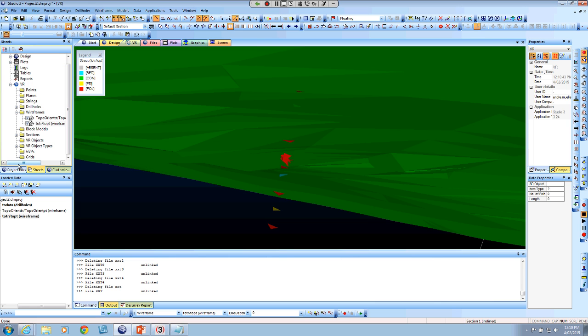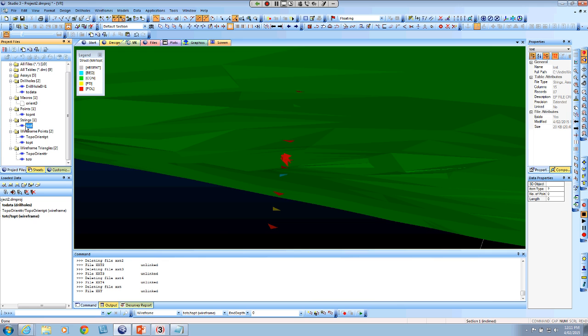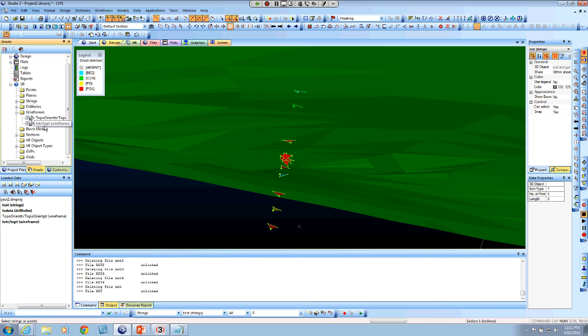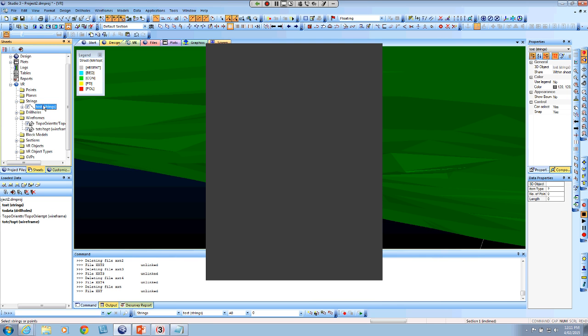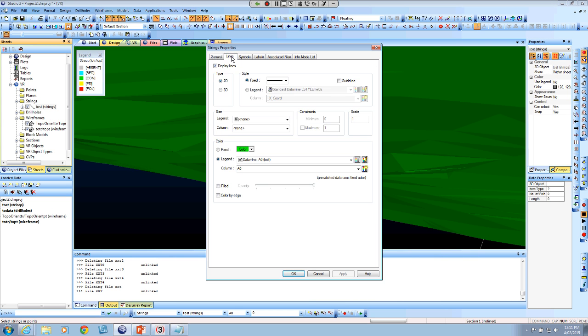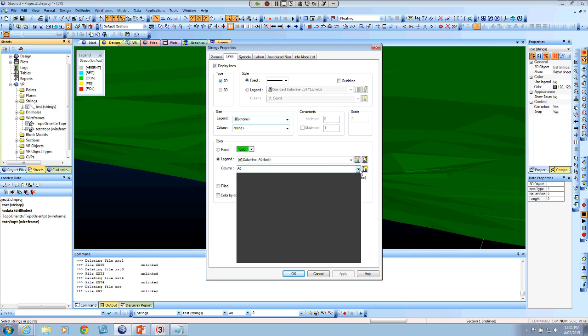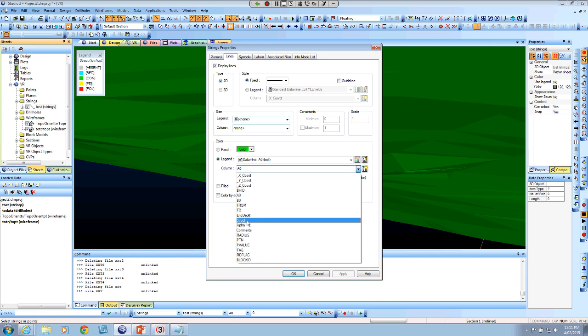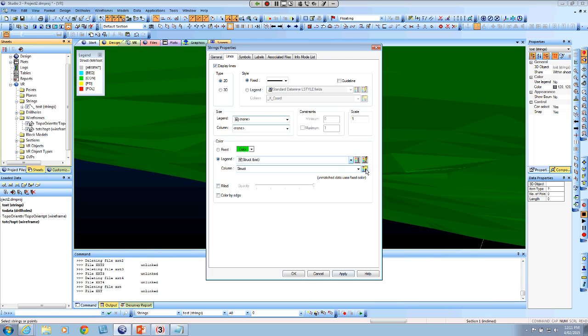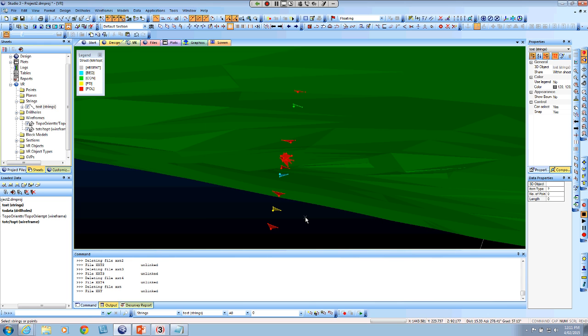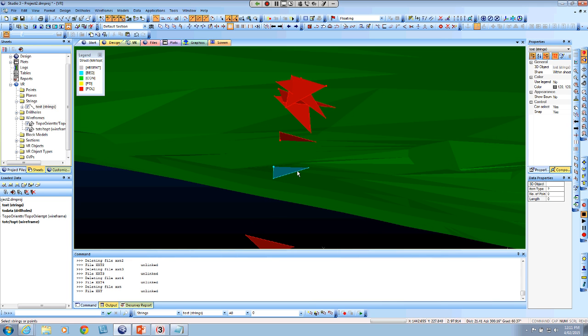If I come back to my projects file, I can also load up the strings associated with this. Now, the strings are a different colour, so of course we need to come over to the Sheets window and colour strings based on the structure as well. If I double click on string properties, select lines, and then select structure, hit the default, hit apply, hit OK. Now you can see each one of these strings has the same colour as the triangle because it's based off this legend.